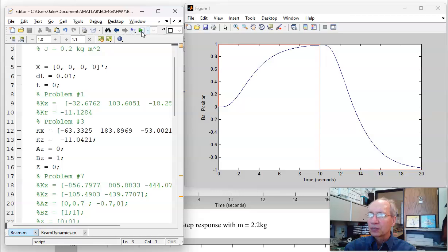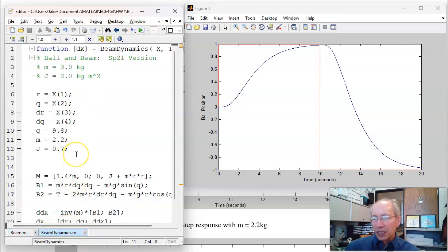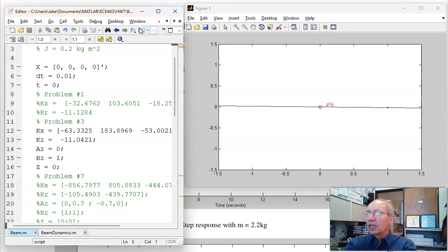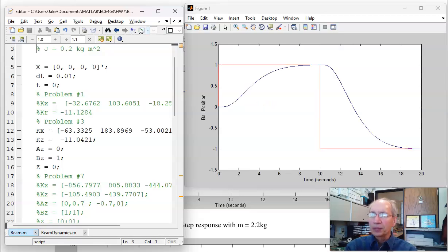And it does. Okay, that's for the nominal system. Suppose instead the ball was 2.5 kilograms. That means I'll have a constant disturbance and a constant set point. Now tell it to go to 1, and it goes to 1. That's what the integrator does for you. The integrator forces the steady state error for constant input to be 0. It will track as long as you're stable.